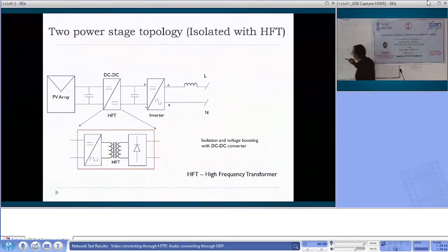So we have the equation omega phi m, 4.44 f phi. That is the equation of a transformer, voltage, right? This means your flux density is much lower. If I write the flux, it is A into B. So this is the area, and the core size will be inversely proportional to frequency. So you've got kilohertz, so it just shrinks by a factor of 20. If it is 50 hertz and you compare 50 hertz and kilohertz, it will be much reduced.